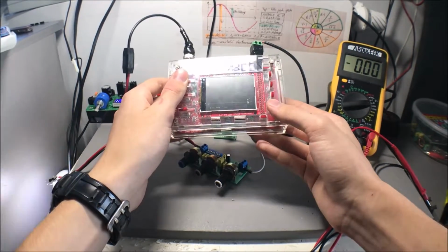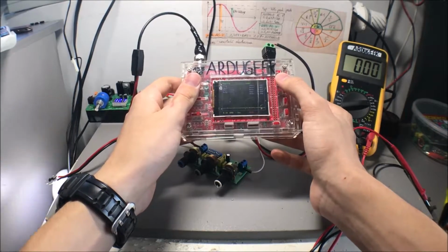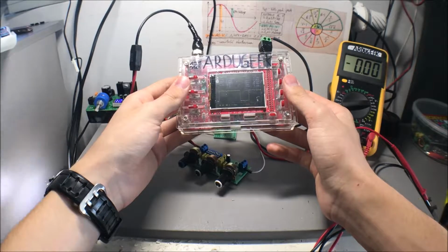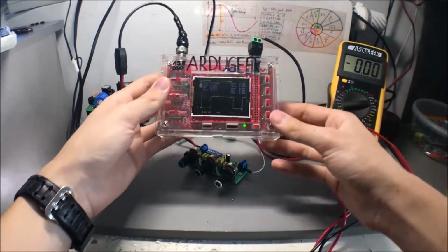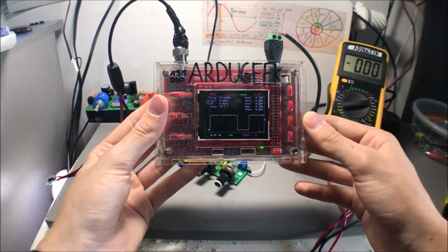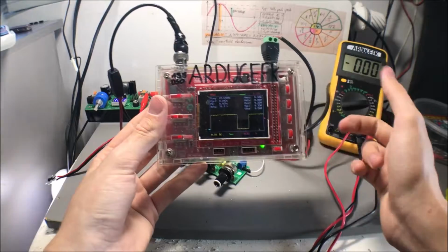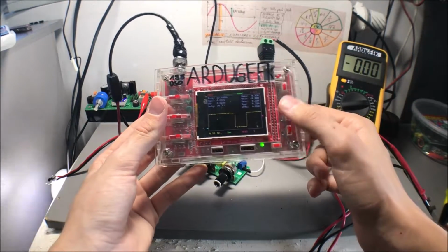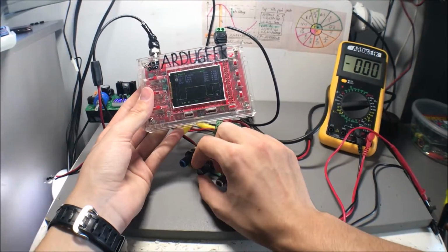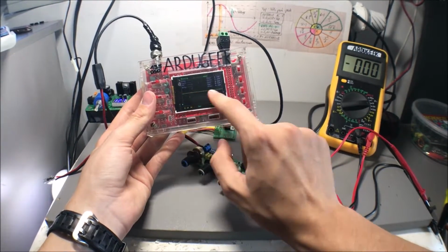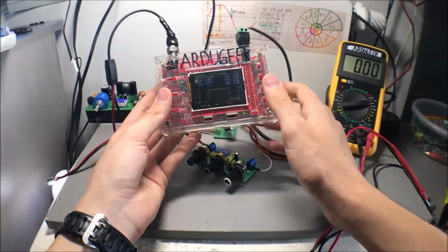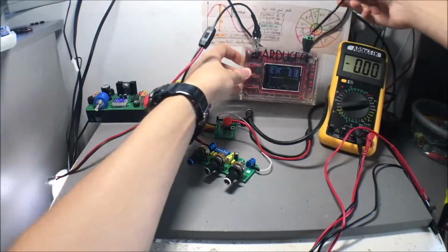Let's see how well we have calibrated the scope. Let's recalibrate it, and then yeah, 0.3 volts peak to peak. So the multimeter just doesn't show it here. As you can see, this is the current that is drawn, and it is mainly the same as we have set it on a normal DC level. Of course when I am switching it, but then when it's constant, as you can see, the maximal current is still the same.